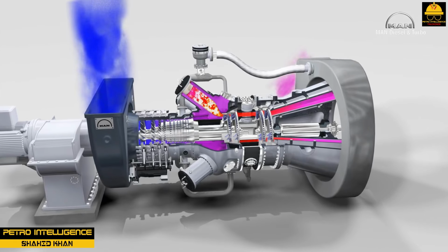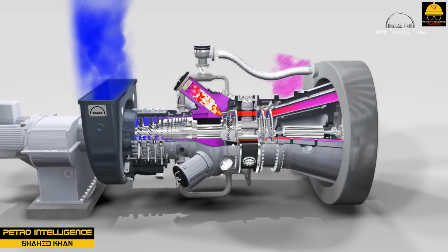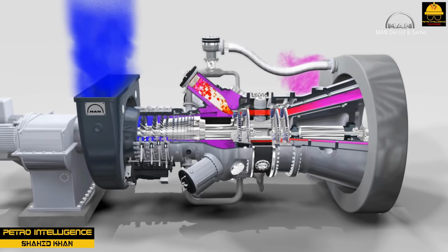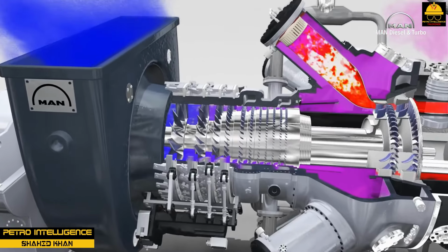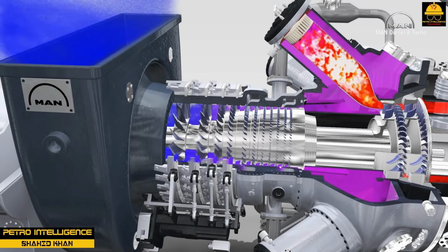The gas turbine system mixes compressed air with fuel in a combustion chamber. A spark plug ignites the mixture, which is directed into the suction side of the gas turbine. The hot combustion gases rush into the gas turbine, causing the turbine wheels to turn. Hot exhaust gases are discharged from the body of the gas turbine.